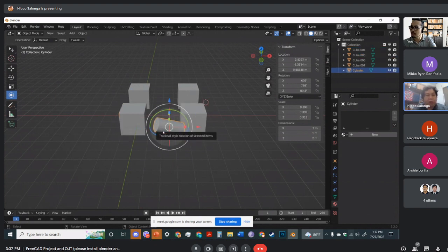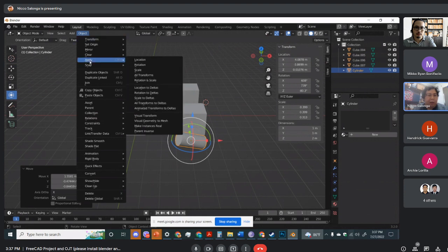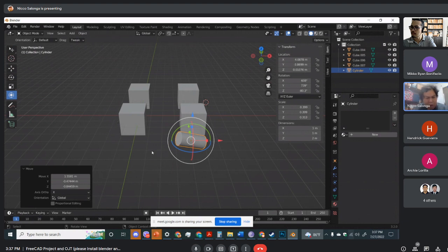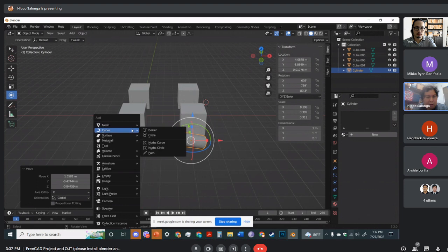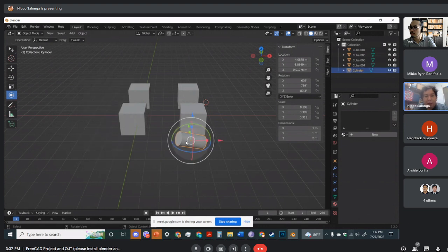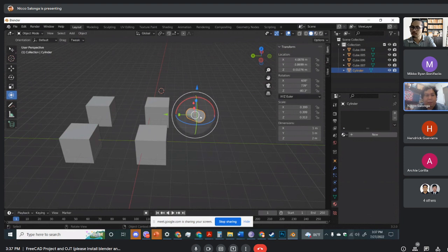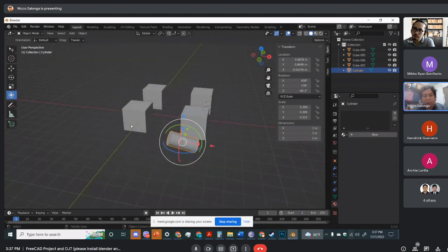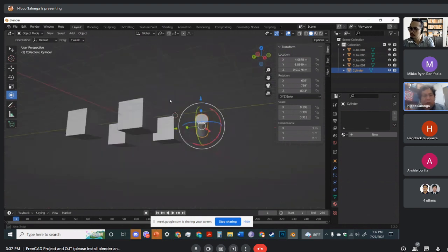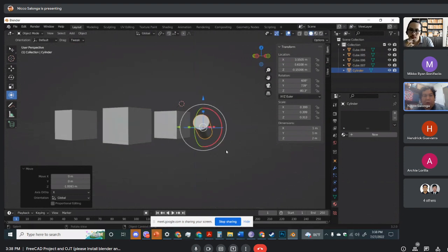Once you've made your shapes, it's a good practice to select everything and basically do Object, Apply, All Transformations. I think it was Shift A? Or was it Control A? Ah, yeah, Control A, and then all transformations. It's not gonna look obvious now, but when you're making animations with moving parts, or when you're reshaping the shape into some other shape, or using other tools here, it's gonna be really important to do that. For now, don't think you have to worry, but you'll probably need to do it when you're working on whatever project you'll be working on later. We'll discuss that later.